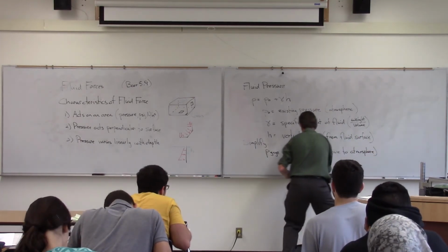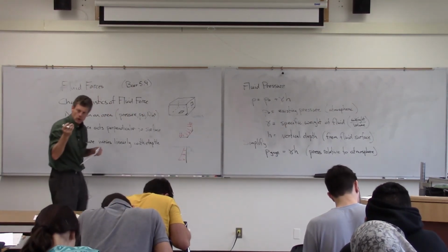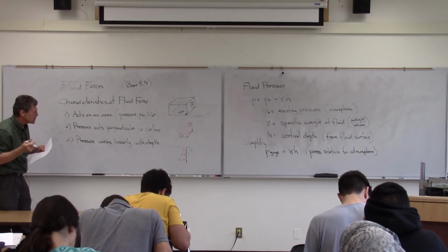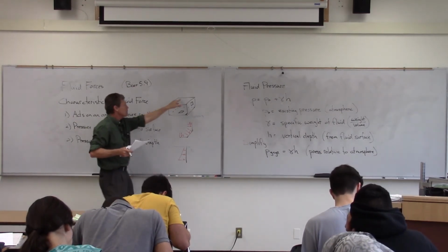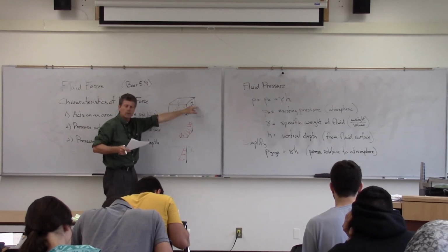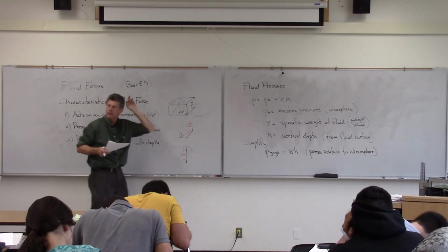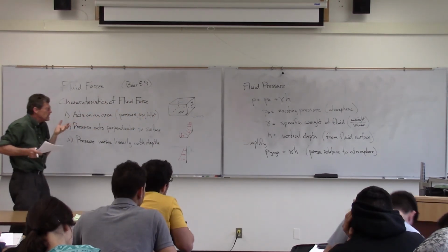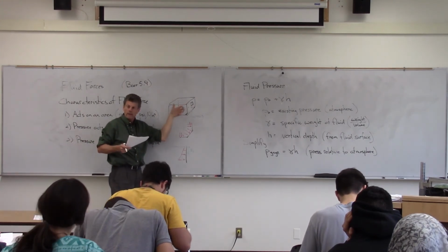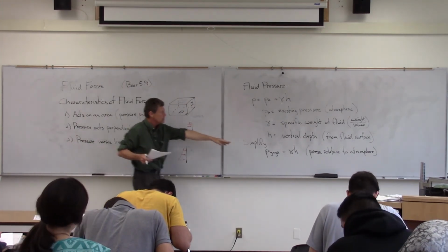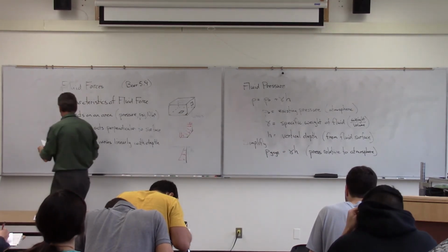Now, we'll simplify this by using just simply the gamma. We'll use what we call the gauge pressure. In most calculations, you'll see simply use the gauge pressure. Again, think about a pool. If I'm considering the atmospheric pressure, well, the atmospheric pressure is also acting on the ground and on these walls if it's an above ground pool and that sort of thing. So I'm not really interested in that. What I'm interested in is the pressure that's going to cause this thing to break, that difference. So we'll be using this gamma h as our tool for calculating pressure.